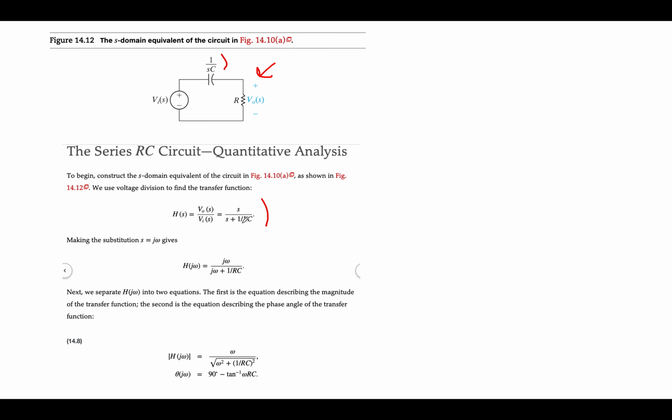We then do our step that we do when we're finding frequency variation in the transfer function: we substitute j omega for S. So in this function, we've substituted j omega for S. We then find the magnitude of both numerator and denominator, which gives us the following magnitude function of j omega, and we find the phase.